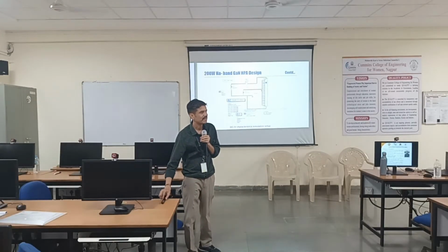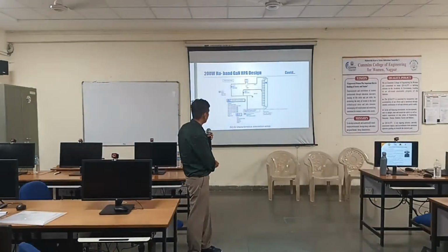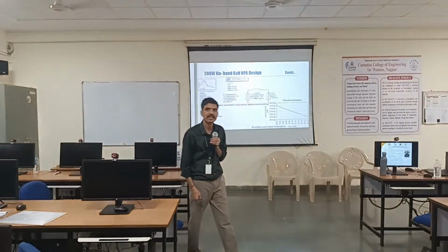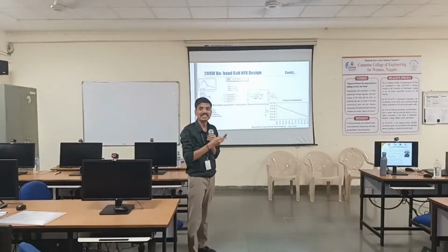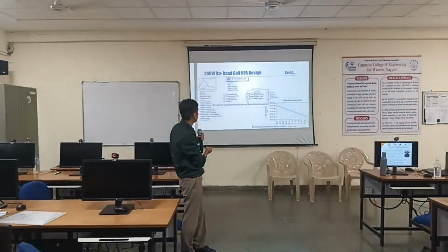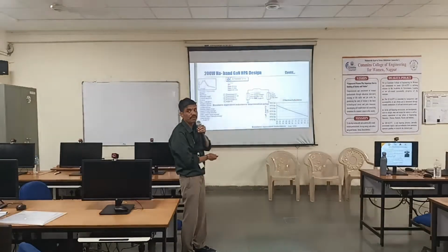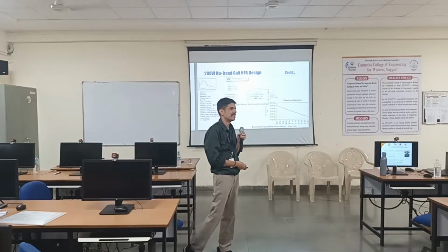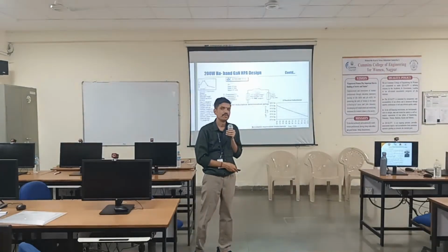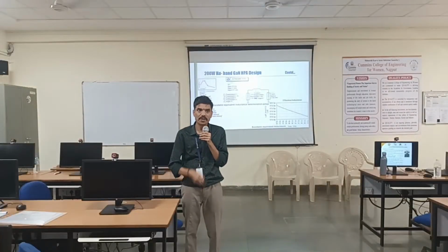How do you connect? The concept is to use bond wires, and these bond wires will be made up of gold. Sir, your gold comes here. Yes, ma'am. These gate pins, you have to use something called a bond wire. And how do we model this bond wire? This is a 3D structure. ADS is a 2.5D software. So which software do you have to use? Either CST or HFSS, to model the bond wire.